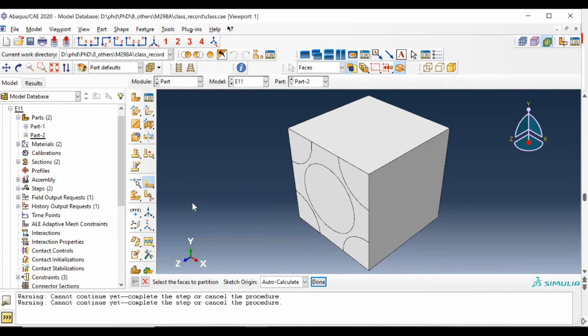Okay, we're finished. Then we're going to extrude this fiber along the depth. So we select this one, the extrude, and select all the edges. Click OK. Then extrude along the direction. We want to extrude along the depth direction. Then that's done. So the geometry is created.